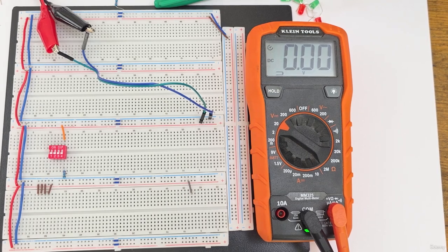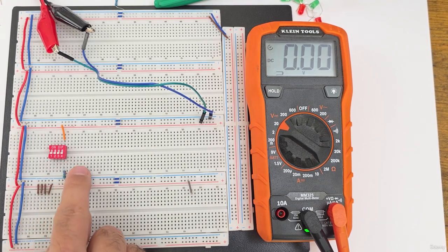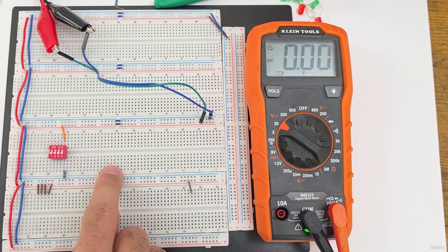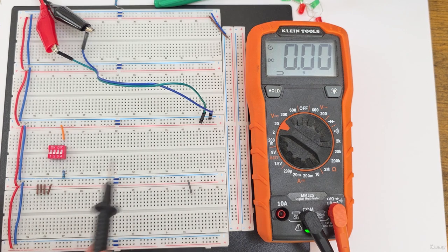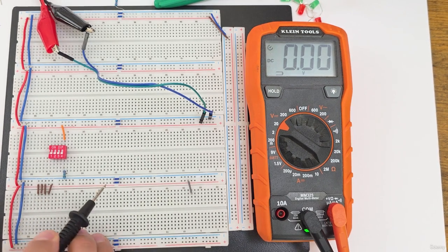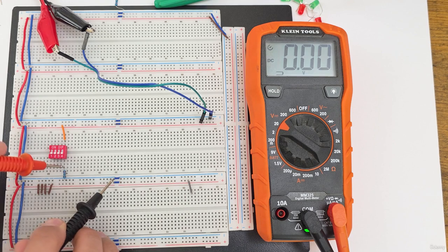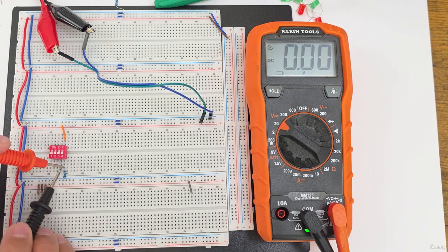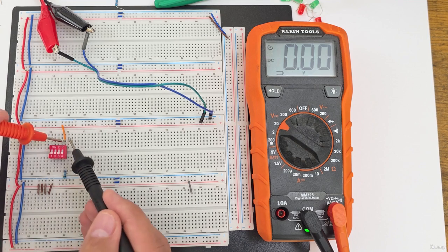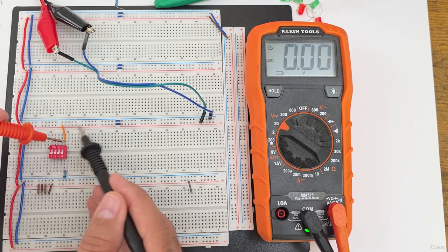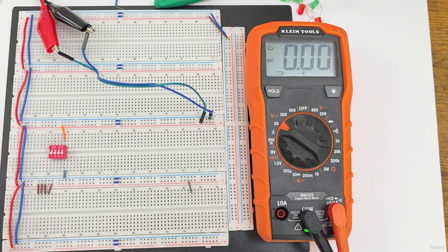And by the way, you can see the output by connecting an LED here, or LED. Okay, so I'm going to do both, but let's start with the voltmeter first. So I'm going to connect this to the ground, this part to the ground here. Where is the ground? This pin. And this pin will be connected to this pin. Why am I connecting here, not here? Because if you put this here, then you are always connected to the VCC. But we need from this pin, exactly like we do here in this picture.